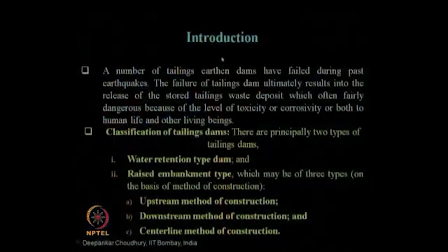Okay. Now, let us come to another subtopic, which is seismic stability of tailing dam. Now, what is a tailing dam or earthen dam? Let us first introduce. A number of tailings earthen dams have failed during past earthquakes. The failure of a tailings dam ultimately results in the release of stored tailings materials or waste deposit, which are often fairly dangerous because of their level of toxicity or corrosivity or both to human life or other living beings.